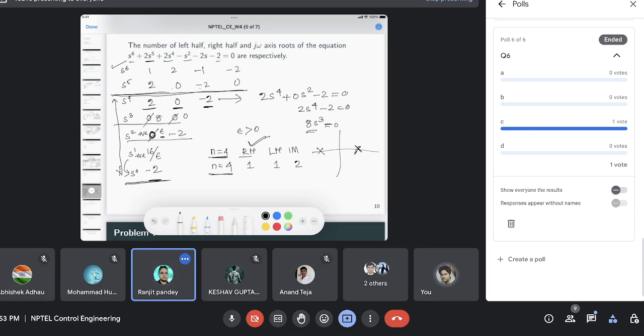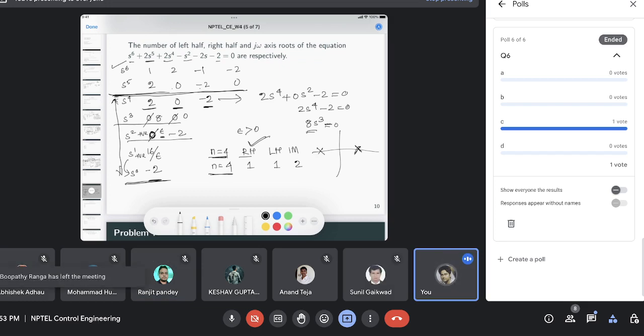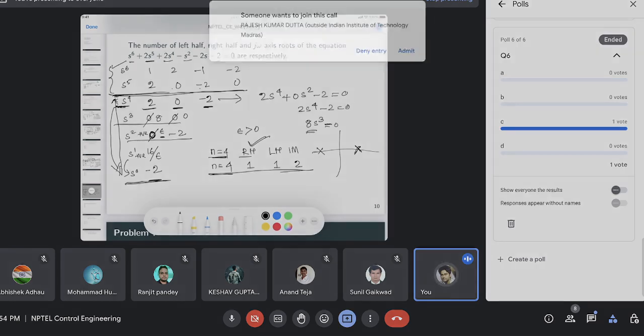Okay, before that I am saying, from S4. Just remember, whenever this auxiliary polynomial happens, it is happening in the 4th row, S4. So whatever analysis comes after that is only for this 4th order auxiliary polynomial. The 4 poles you have already accounted. Whatever happened before that is for other poles that are not in the auxiliary polynomial. So there is no sign change up to even S4.